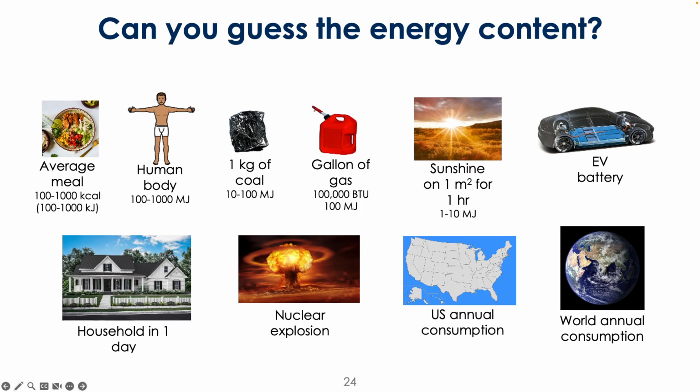Okay, what about the energy content of an EV battery? What do you guys think? Yeah, so 10 to 100 kilowatt hours, so 100 to 1,000 megajoules. And so you can start to contextualize some of the issues here, right? A gallon of gas might be equivalent to a really small battery, and for a full-size battery you might need something like 10 gallons of gas to be equal in energy content.